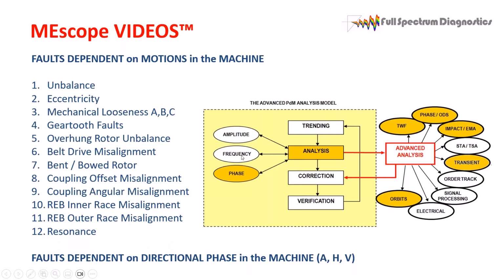It's all at the frequency 1 times RPM, must be unbalanced. So you check the phase and it's not. It's like, huh, that's weird. Check again, and you can't get anything to line up right, and you try a different fault, and you can see what's going on. One problem in the frequency domain, but 12 different problems in the phase domain.